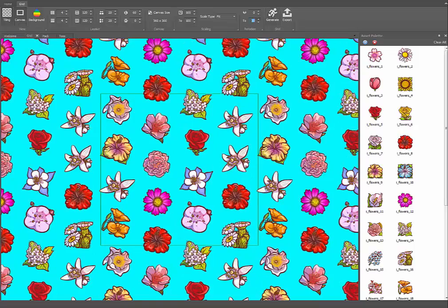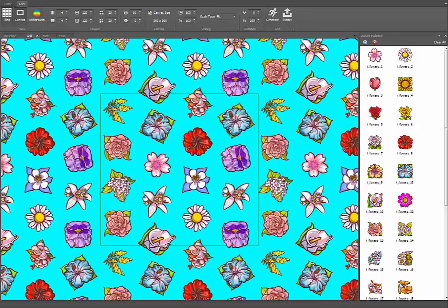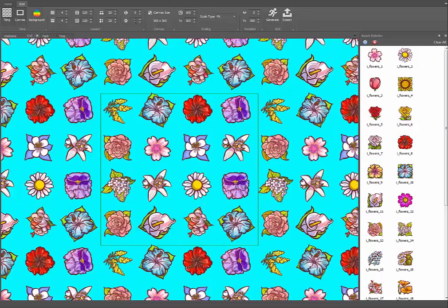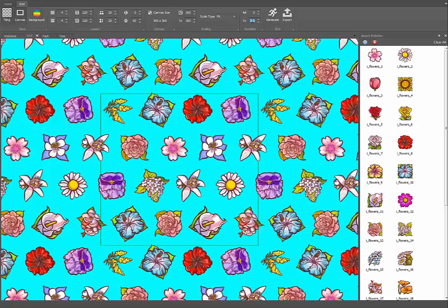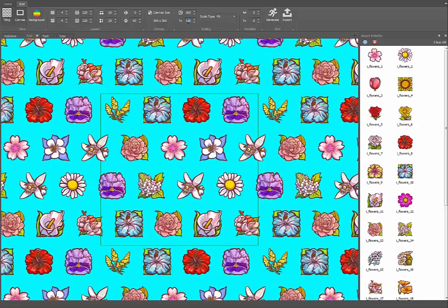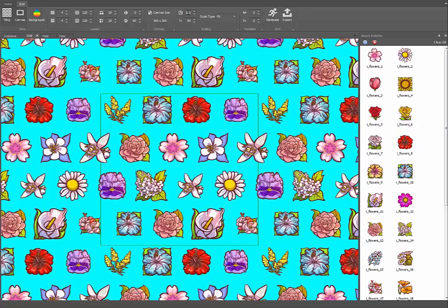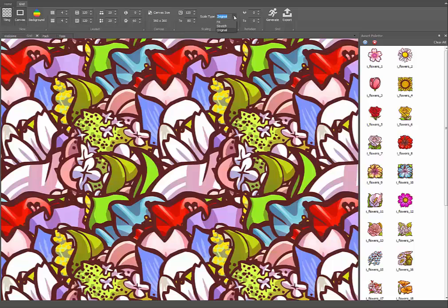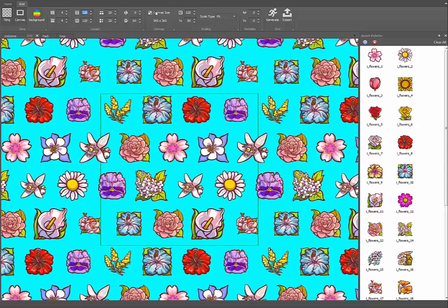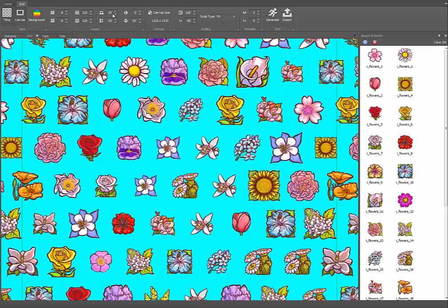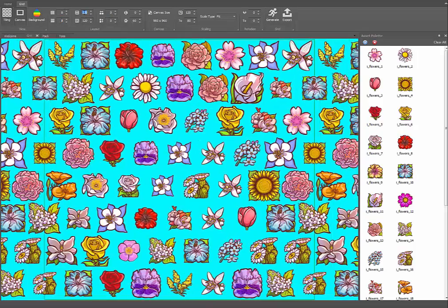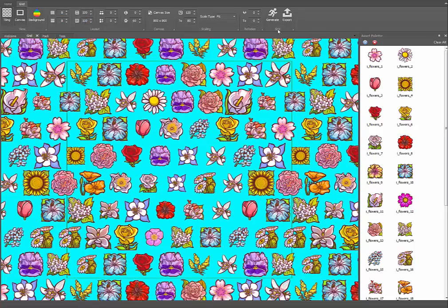I can also choose specific angle and scale ranges. The default scale type is set to Fit, which takes on the grid size you already set. Stretch prioritizes grid dimensions and stretches assets to those parameters, while Original prioritizes the asset's original dimensions and size, ignoring grid parameters. I'll cover this deeper in future tutorials. You can toggle the canvas border and the tiling to see how your pattern repeats. The power in this tool is the rate of quick iteration you can achieve.